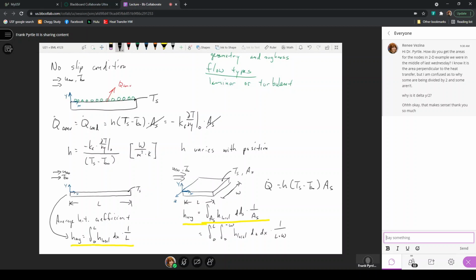So if the fluid temperature is varying as a function of position because heat is being transferred into the fluid, then the thermal conductivity of the fluid, which is a function of temperature, would change. Just the heat transfer coefficient will change. Here, the temperature gradient changes because the thermal boundary layer is growing as it moves along the surface of this plate, and this is an expression of the change in temperature with respect to Y at this position.